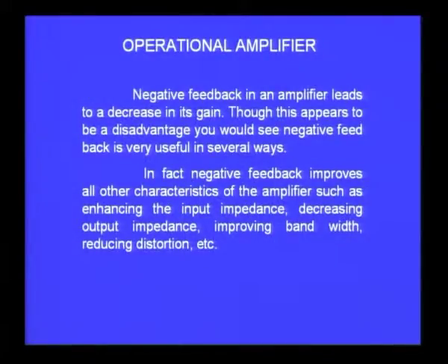You can intuitively guess that when you give negative feedback the gain will decrease, and it is indeed true that when you give negative feedback in an amplifier the gain will decrease. Though you feel that this will be a disadvantage to the amplifier because you do not want the gain to decrease, you want the gain to be more, you can see this is a great advantage in several other parameters of an amplifier like input impedance, output impedance, bandwidth, distortion.